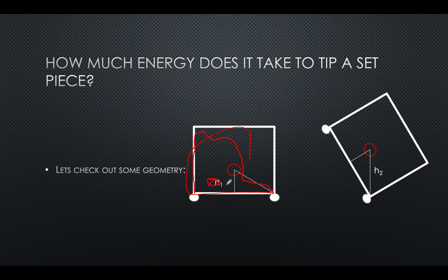Now, once you've done that, there are two things you need to determine. You need to determine the height, where I just drew over this H1 here, off of the wheels, and also the distance to the nearest wheel. So this is what we're going to call L, and then this is our H1 that I crossed out here.